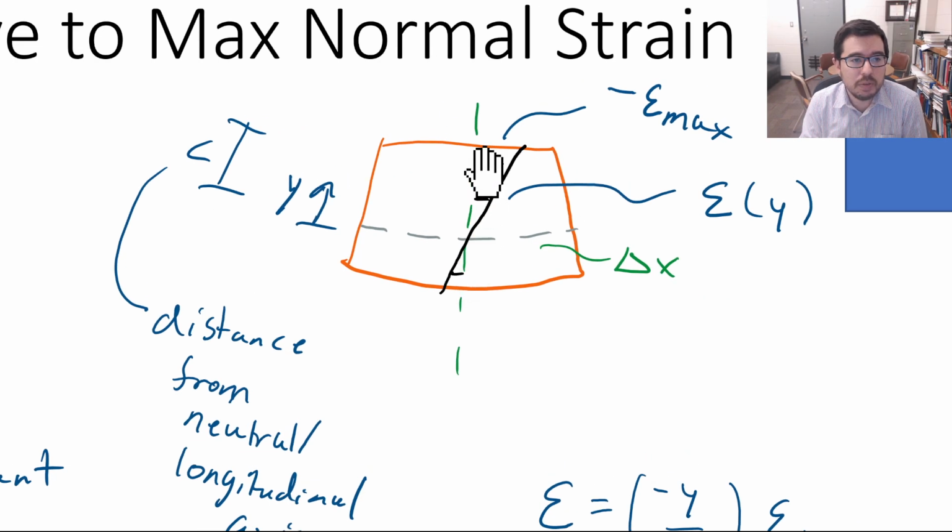So above the neutral axis, or the longitudinal axis, or the neutral surface, we have what we're calling compression. And then when we get on the other side, the line crosses through this vertical line here that's often drawn, and it shows that once it's crossed through, it goes from compression up here to the opposite. So it's going to tension here.